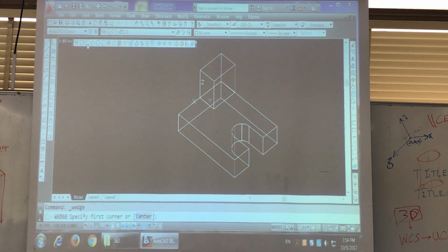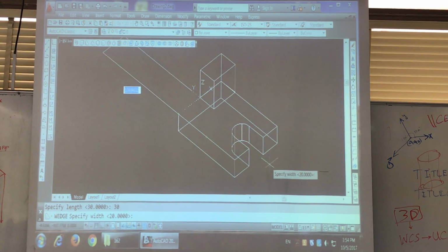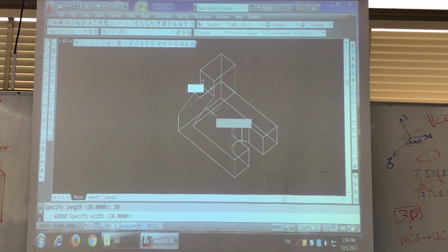So, I will take a wedge, go over here, cube or length, L, enter. What is in the X direction, how much? 30. In this direction, it's moving that side, you see? So even if I am moving my cursor, it is going that side. So if this is happening, the lengths are not getting formed, instead of giving 20, give minus 20. Use F5. Minus 20, enter. There is no F5, this is not isometric. Then what is the height? 25.